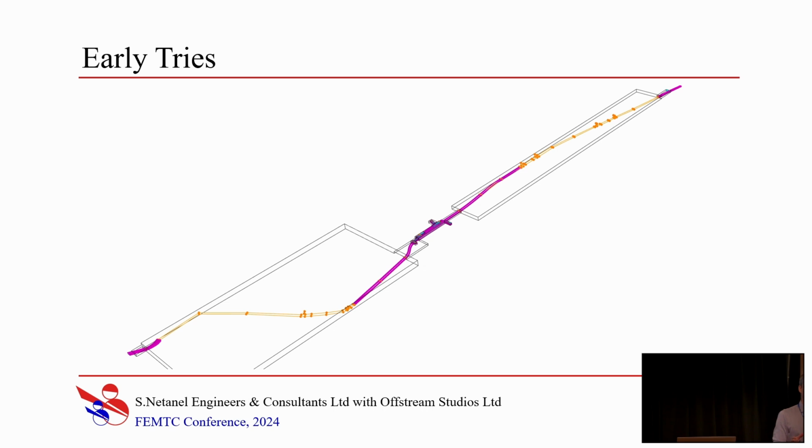Not crashing, just halting. I suspected this somewhere in the 1D calculation that there was some kind of loop. And my immediate suspect were the cross passages. Those are passages between the two tunnels. And in the 1D calculation, they are only used for air leaks between the tunnels. And theoretically, they could loop flow between themselves. Tried the simulations without them. That worked.